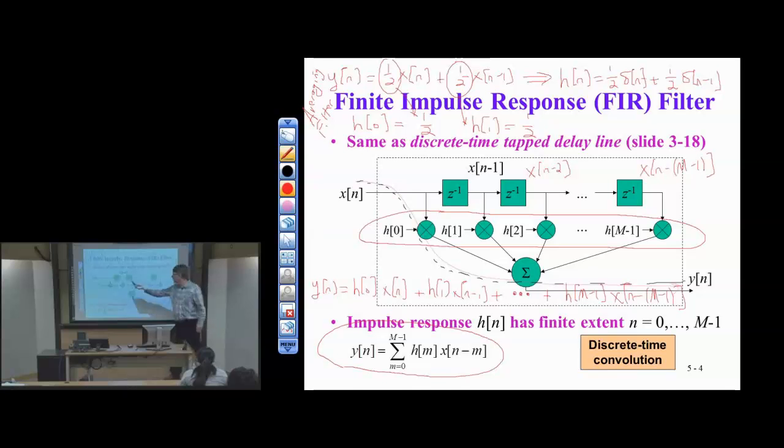So when you think of convolution, as we have thought about it in signals and systems, and will think about it again this way, we hold a signal in place, like h, the impulse response, and we flip and slide the input signal across the impulse response. The flip is because of the minus m, and the slide is because of little n. Little n is the outer variable in the convolution. It turns out the flip and slide is actually implemented by the delay line.